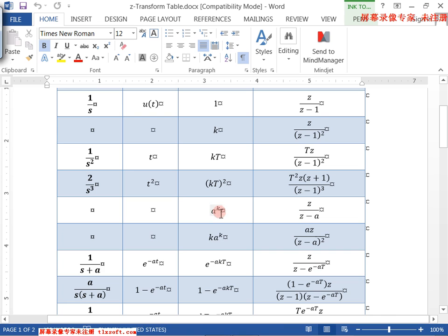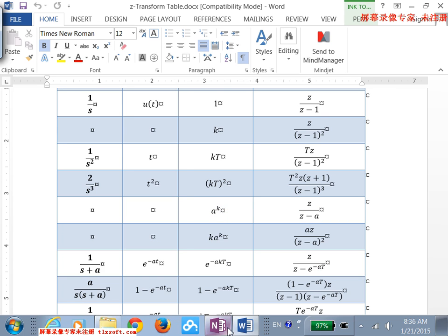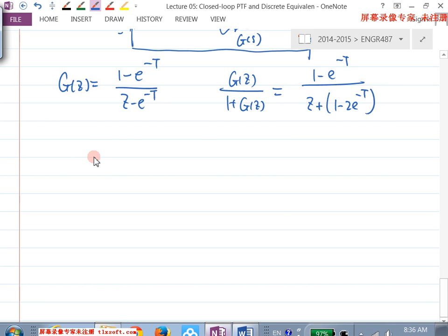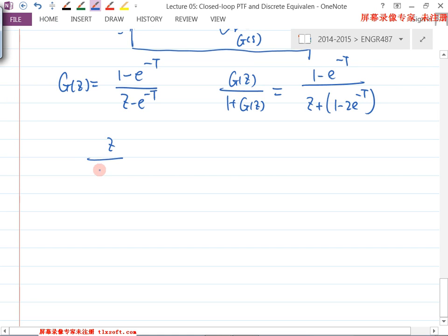Which means, if you have something like this, you know this is going to be like that. Now, when we do the inverse Z transform for a particular pulse transfer function, it may not be as simple as this. Maybe there are different poles, multiple poles there. But you can always use the partial fraction expansion to simplify that into different components, adding them together. But ultimately,